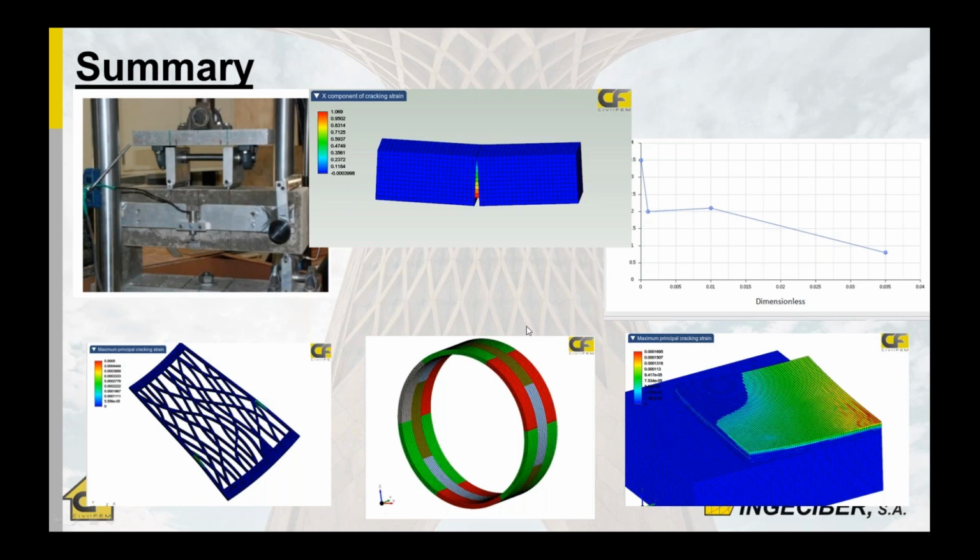Also, you can obtain a detailed model with the full lining and the real pressures and compare with the small test. And of course, there's a really big application for pavements, to avoid cracks due to temperatures and sink rates, to calculate the behavior of these slabs, and also to consider different thicknesses and different fiber amounts to avoid crack generation in these models.